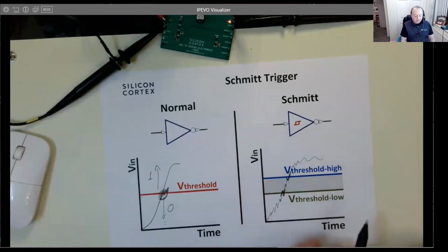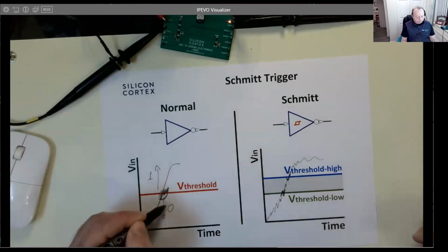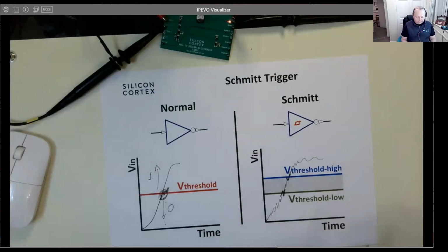Because while I was trying to test it, I just couldn't understand why I wasn't seeing this dithering in an ordinary gate. And it was because they now put it into standard gates as well, which doesn't seem unreasonable to me. There's no mention of it in the datasheet, but it was evident on the screen.